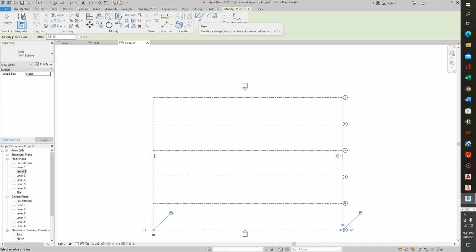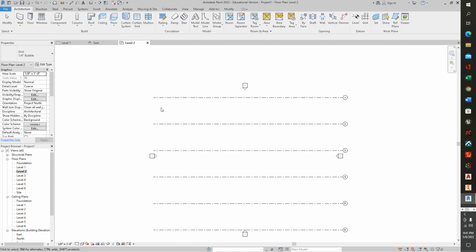But we would like to have some cross lines as well to make a grid. So under draw, we have lines. Again, we'll draw some downwards now. So we'll go from the top, and you'll notice that the angle changes. You can tell what angle you're going to draw this at. Actually, I don't want to do this at this point because this is putting our offset from where we're at to 25 feet out of where we're drawing. So we're not in line with anything that we'd like to be. Sort of are, but we'll escape out of that.